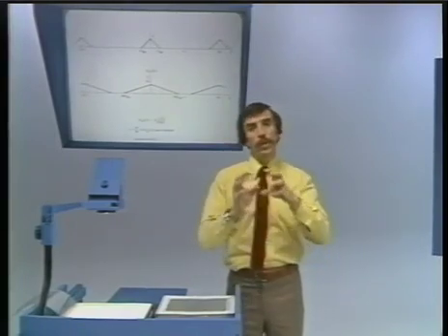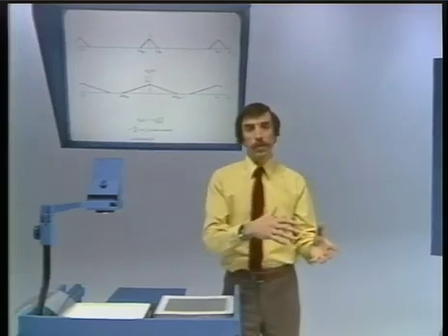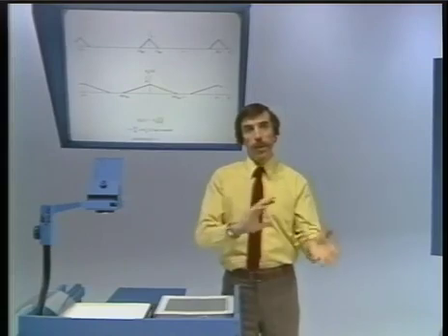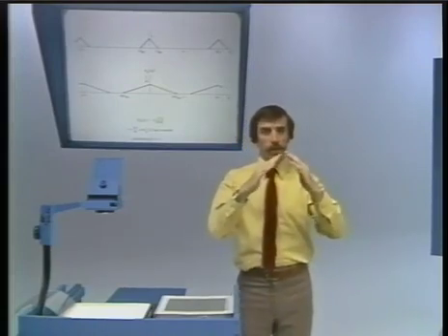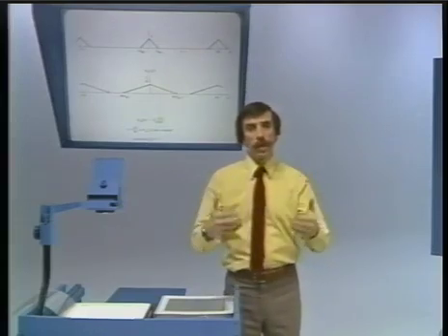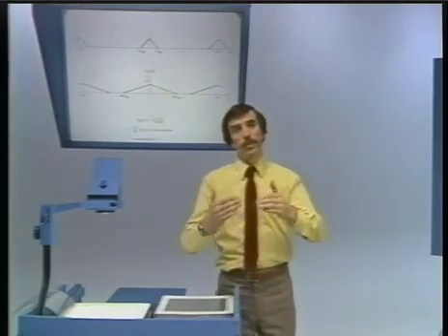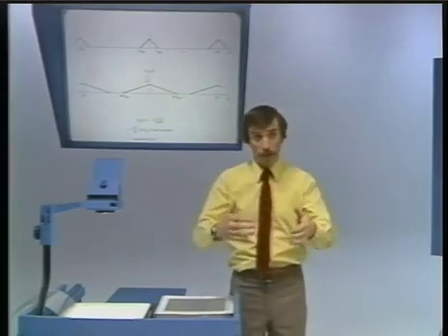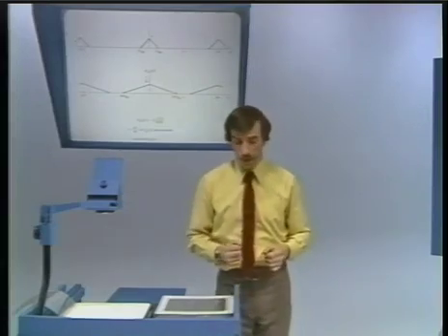The relationship between the spectrum of the decimated signal and the spectrum of the sampled signal is true whether or not we have aliasing. But being able to clearly associate it with just simply scaling of the spectrum of the original signal assumes that the shape of the spectrum of the original signal is preserved when we generate the sampled signal.